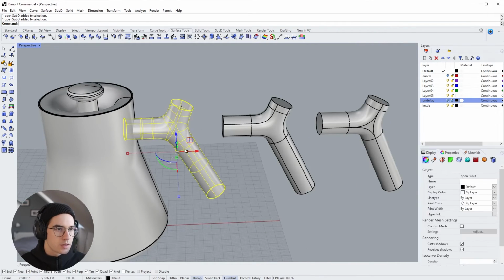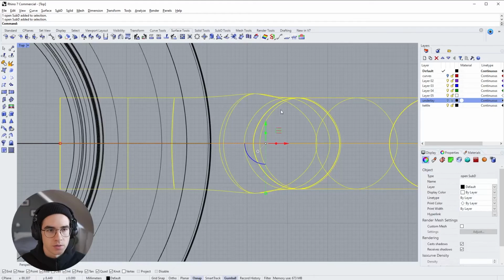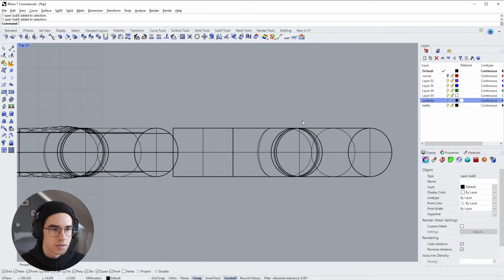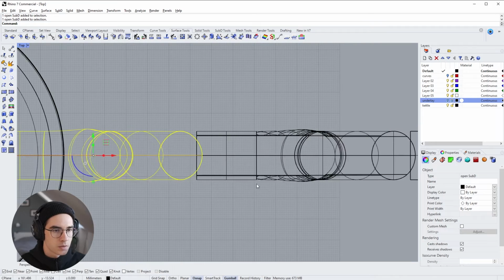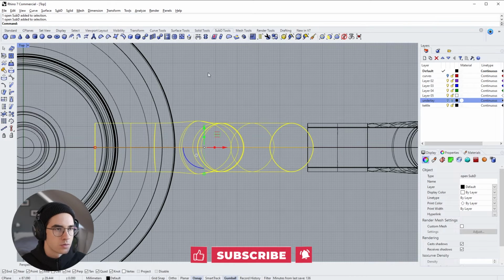A few tweaks we need to do for this one are apparent if we go to the top view. You can see that it bulges out. So this is one of those drawbacks. Of course, you can use it for design models, but for final production surfaces, it's not meant to be. So you can see the first one that we created with the flat sides doesn't have this bulge. The one with the patch surface does have the bulge, but since we are still in the subdivision tools, we can just tweak this a little bit.